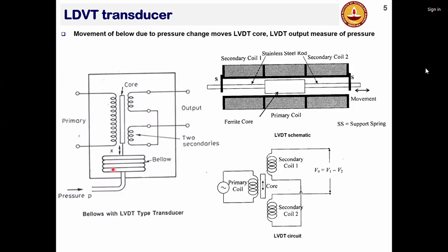I mean, you should really know the construction of bellows. This is how they look at atmospheric pressure: closely packed, with no room for compression. They cannot take a compressive load as such, so they would only expand.